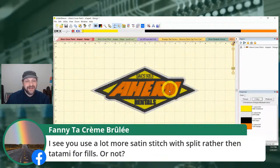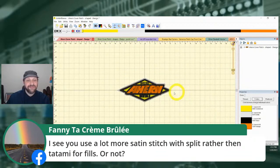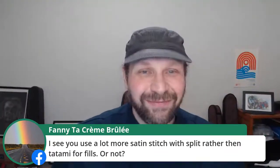If this were any bigger, and when I did jacket back versions of this, I absolutely made those big fat letters into fills that had borders on them. When I get big enough, a bordered fill is nice and crisp and it looks good, and it looks better than trying to render a turning fill. I don't usually like a standard tatami fill with turning stitch angles. Not my favorite thing. So hopefully that makes a little sense.